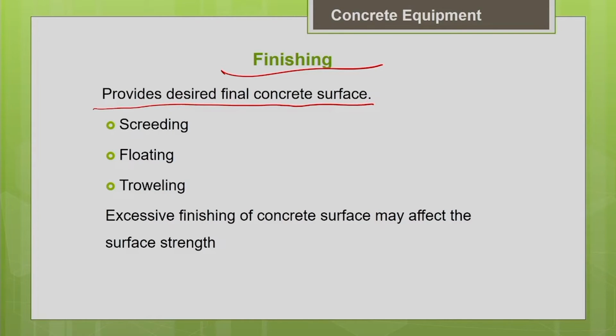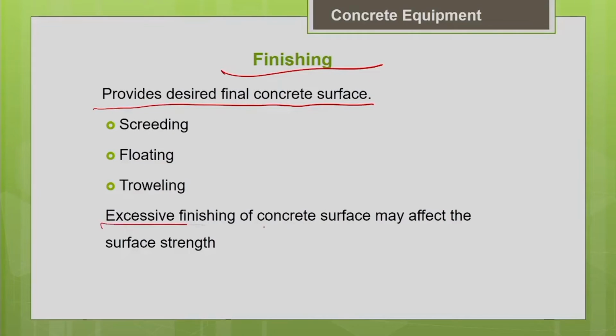But generally speaking, after consolidation, whatever work we try to do with the concrete will generally harm it. That is why after consolidation, we should not try to do excessive finishing. Very commonly in project sites, you can see that the finishers try to manipulate the surface of the concrete by adding water and doing finishing, so that they get a very good surface texture. That is really a wrong practice. We should never do excessive finishing, and we should not add water to manipulate the surface to get the desired texture.